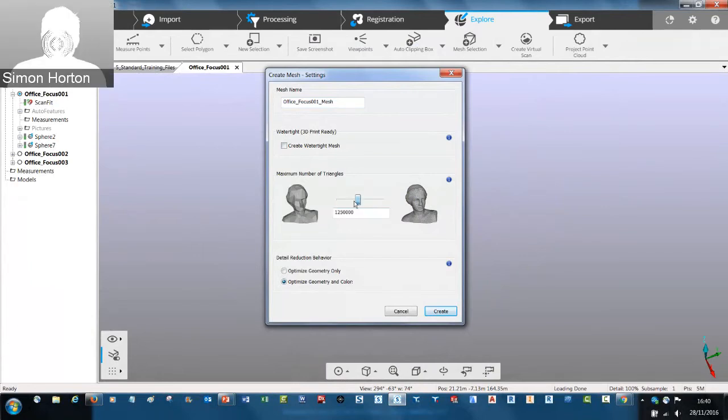Now, if you need to mesh a larger area, if you use the clipping box along an axis tool, which I've just done for WebShare, if you set the distance between the clipping boxes to be 0, then whichever clipping box you select and have active, that will equate to what you can do in here. So you can get more than 40 million, but you can only get 40 million per selection. So it's quite quick and quite easy to do if you need to get out a larger area.